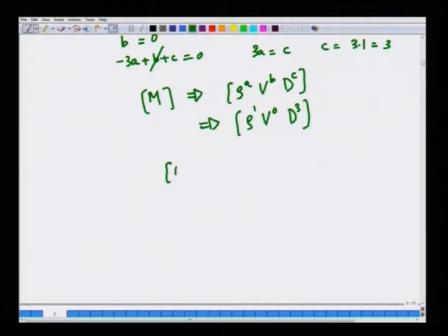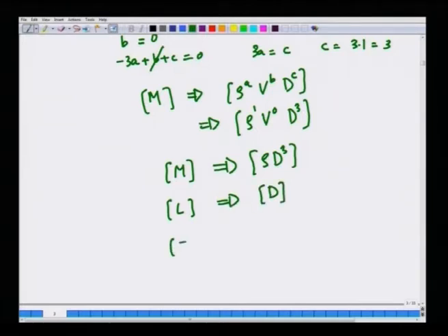So, this means that you can get a dimension of mass by multiplying rho by d cubed. That makes physical sense, because rho is mass per unit volume and you are multiplying by d cubed, which has dimensions of volume. So, you will obviously get a mass dimension. Likewise, you can get the other two dimensions in the following way. Okay. So, this is the mass dimension. The length dimension is trivial, because you can choose d as the length dimension, and for the time dimension we can just choose d by v. Okay. So, d by v is a time scale.